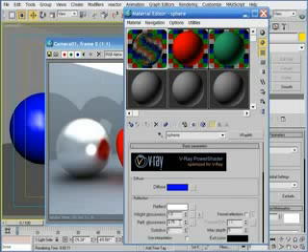So when I unlock the two, the reflection glossiness is automatically kept at 0.75 and the highlight glossiness is restored to its default value of 1.0. What these two settings now mean is that while the entire surface of the material wants to be blurred, the highlight itself will not be blurred because its glossiness value is 1.0.